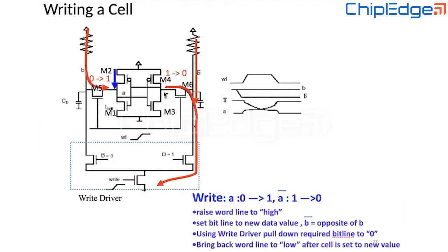So what do we do? We ourselves, in the SRAM design process, depending upon what data needs to be written, discharge the corresponding bit line. Suppose this 1 needs to be converted to 0, then this side of the bit line will get discharged. We will discharge based on whatever is the data to be written. If we want to write a 0 this side, we will discharge this bit line. If we want to write a 0 the other side, we will discharge that bit line.